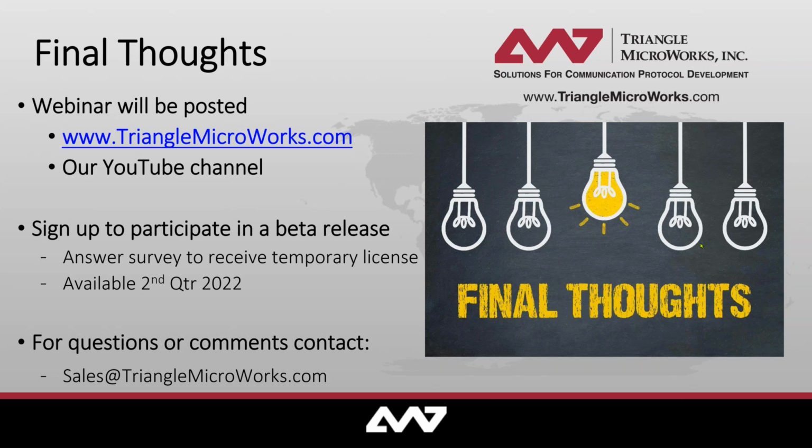We can issue control tests where you operate a control on your SCADA system, and it makes its way through the gateway and down into the remote device, which would be simulated, so we can actually intercept the control in the simulated device and make sure that the information is correct and things like that. We believe that's a very significant use case for this type of thing, this point-to-point testing or closed loop.